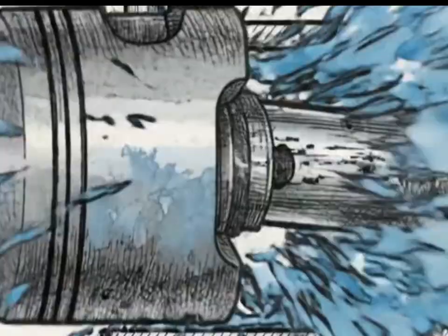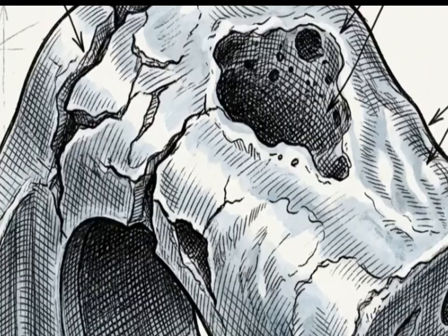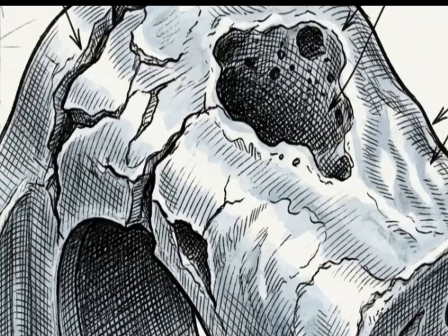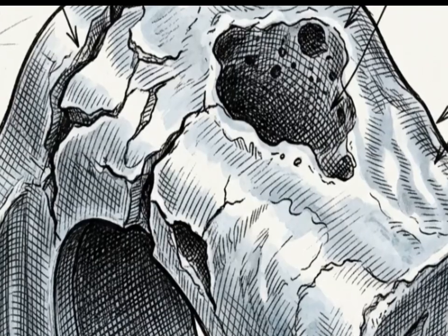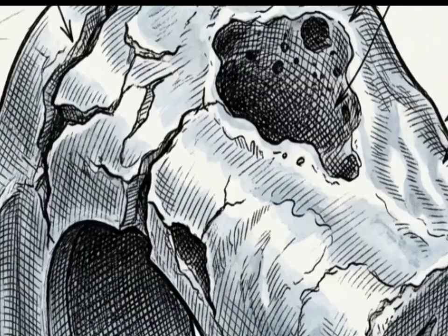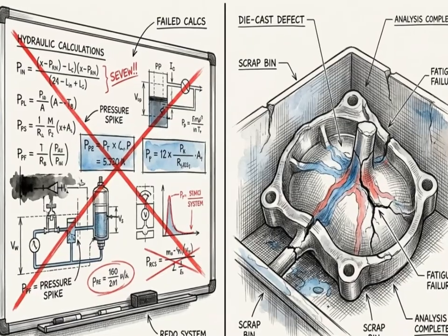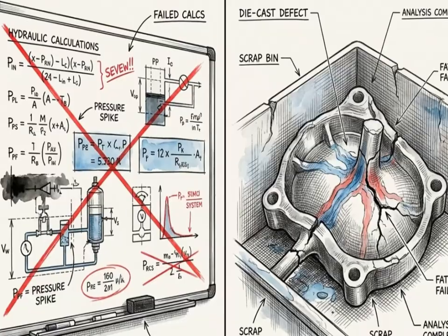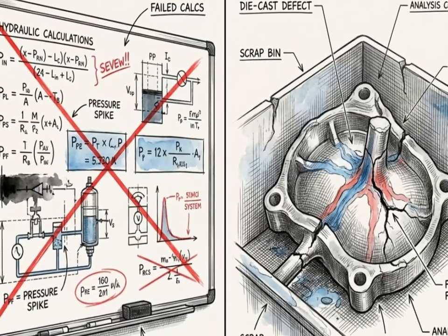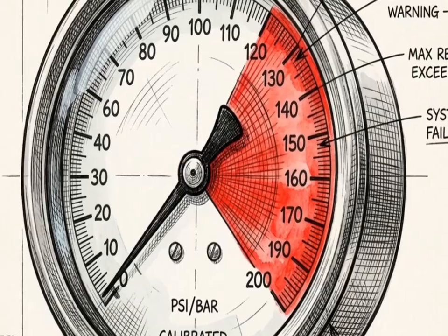The heavy hydraulic piston stutters and end filling speed violently drops. This lack of terminal velocity allows the metal to cool rapidly, creating cold shuts, gas porosity, and visible flow marks on the final part. When the math fails, the casting fails. The habit of leaving pressure fixed is mathematically responsible for this end stage quality collapse.